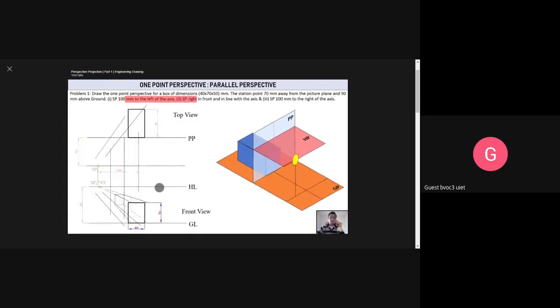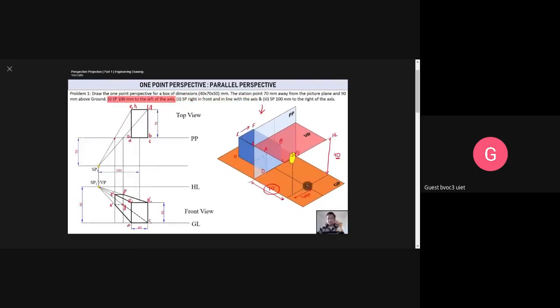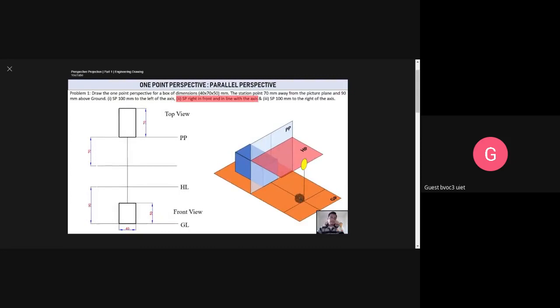Just watch this. Now we are here. Let me just show that once again. The perspective will shift slightly as the observer is shifting right at the center. How to do this? No nomenclature, nothing of that sort. What I'll try to do is, first of all, let me mark the station point. Station point 2. And this is the corresponding vanishing point.